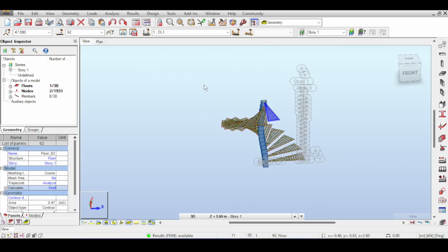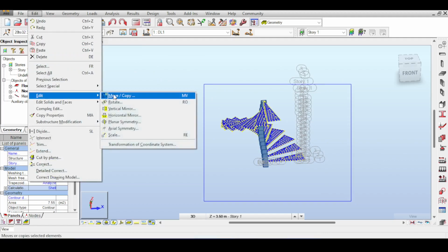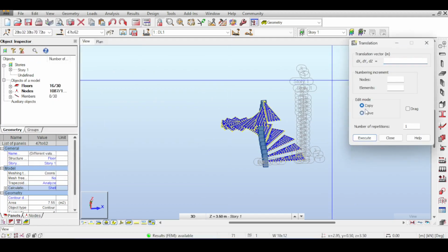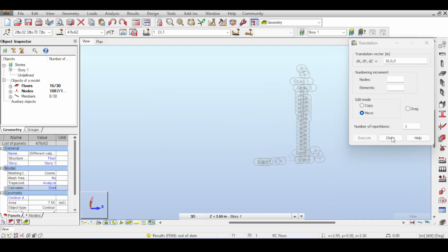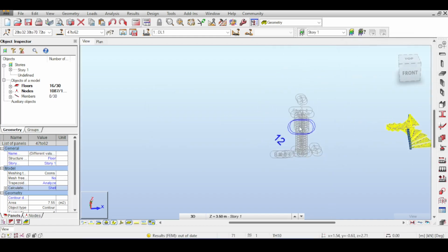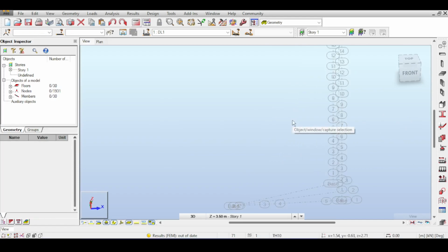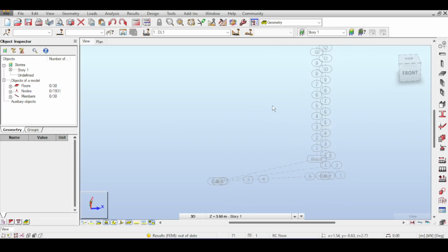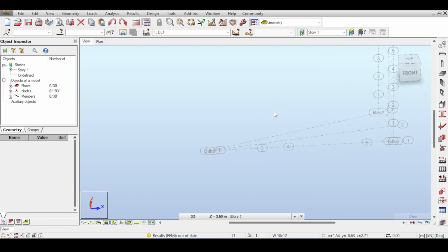So okay, let's take it, edit, and throw it away. So edit, move or copy. Let's move it 10 meters along the x-axis this time, not the y or z. So we throw this away, and now we have another staircase on the right side. Going on with this, we now make a concrete circular staircase. And what I will explain now works for both concrete staircases and concrete ramps for cars.